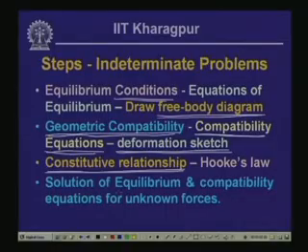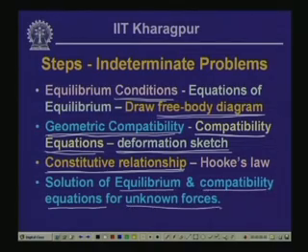Once we have these two sets of equations, we can solve for the unknown forces. So, the solution of the equilibrium and compatibility equations is utilized for finding the unknown forces. These are the steps that are necessary for the solution of an indeterminate problem.